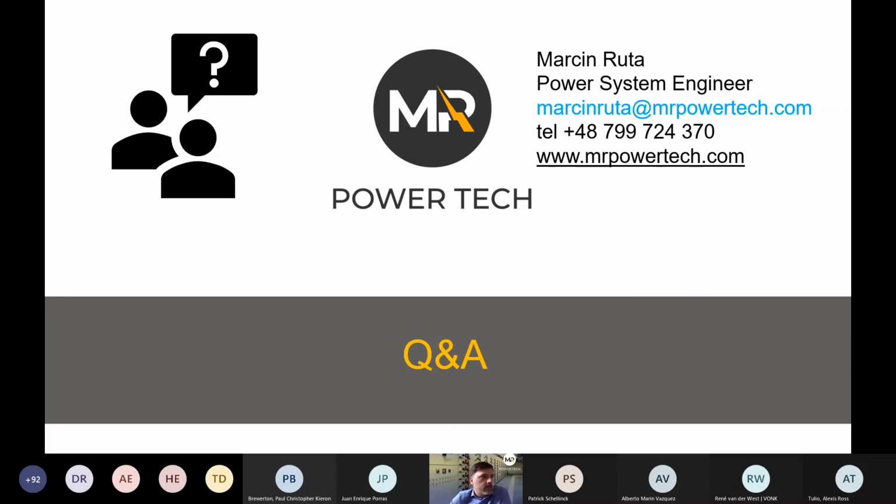As you mentioned, 95% of projects use IEEE 1584. If we did our short circuit coordination study based on IEC, and now we want to do the arc study using IEEE by ETAP or EasyPower, etc., do we have to rerun our short circuit study based on the IEEE standard, or is there no obligation? Either IEEE or IEC short circuit study could be used as an input for the arc study.